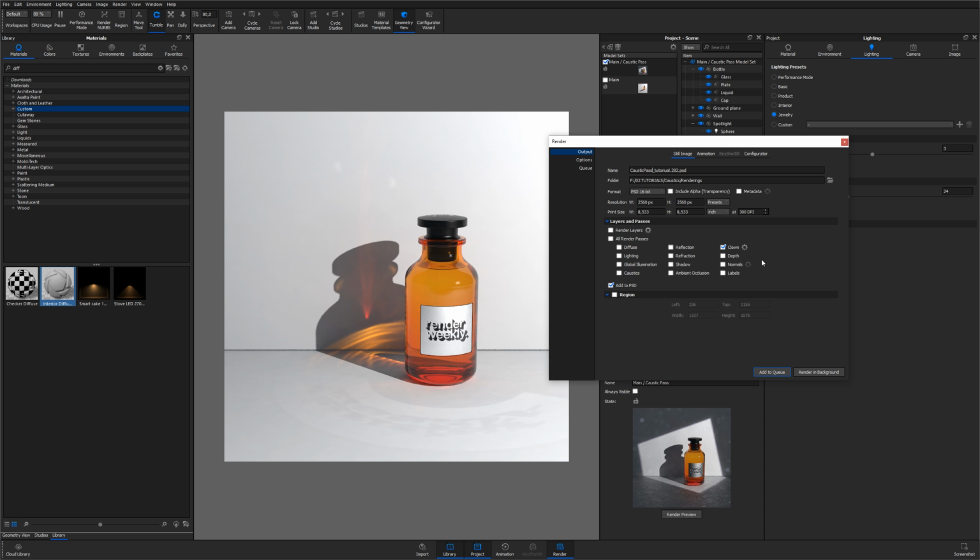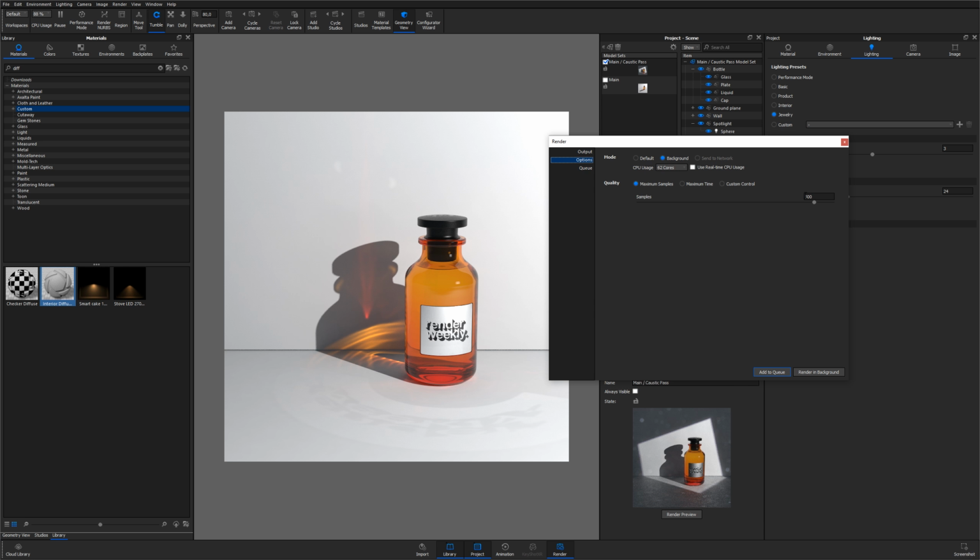In the Photoshop file, we want to include caustics as a separate pass, so we have that on its own layer. We also want to include reflection and refraction because we can use that in post-processing to enhance the look of the glass and the liquid. No need to output the clown pass again, we have that already.